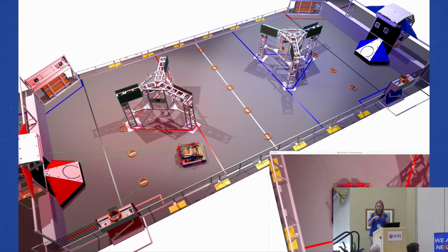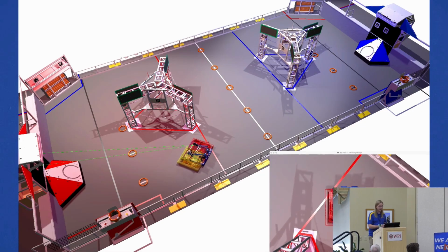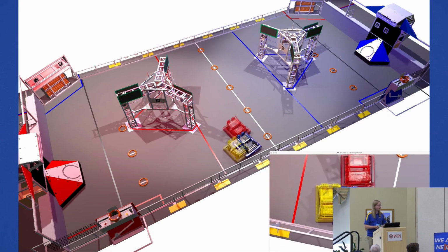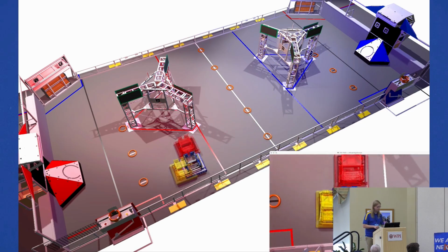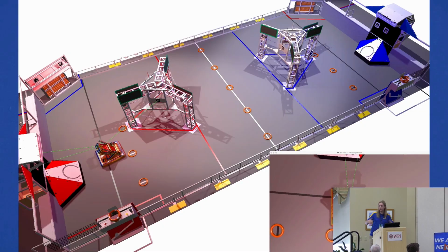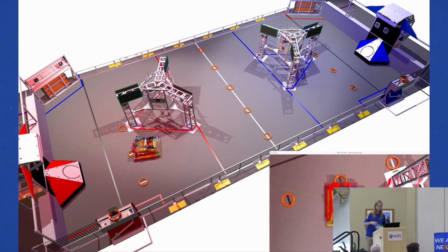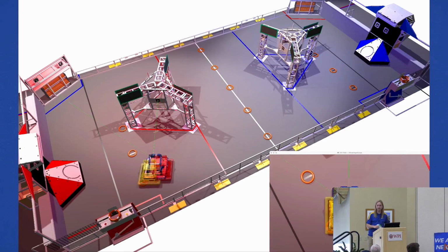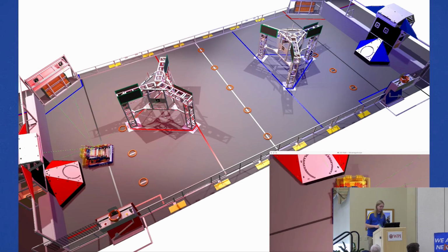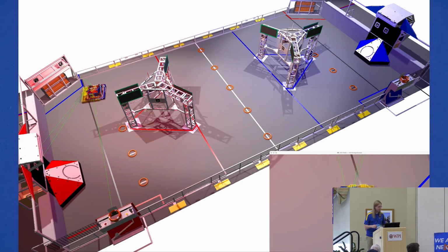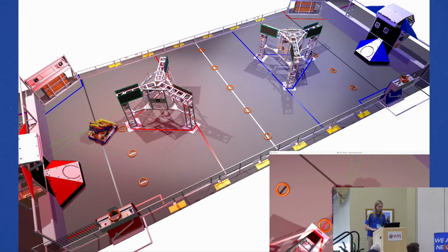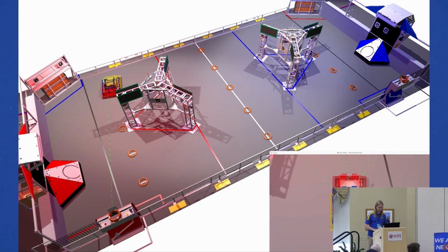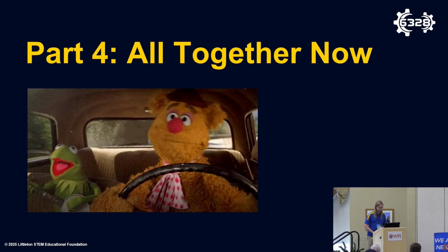You can see that becomes offset when we're in a part of the field where we don't see a lot of tags. And finally, the red robot, which is by far the noisiest, has all of our cameras and our full field of view, but we're only using very simple filters. We turned off most of the logic that we've developed, and you can see the estimates tend to be really poor. So really all of these things have to come together to create a nice global positioning estimate.